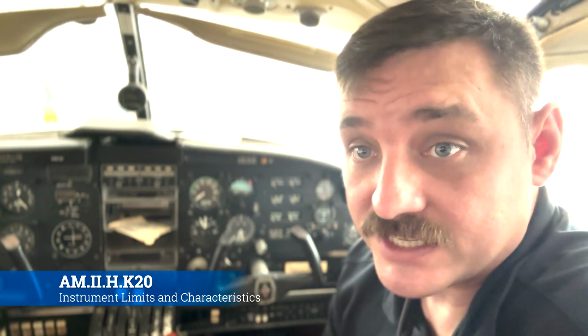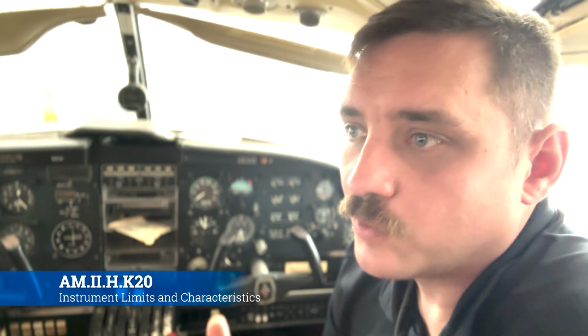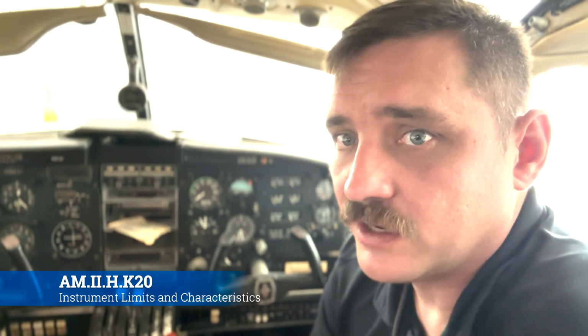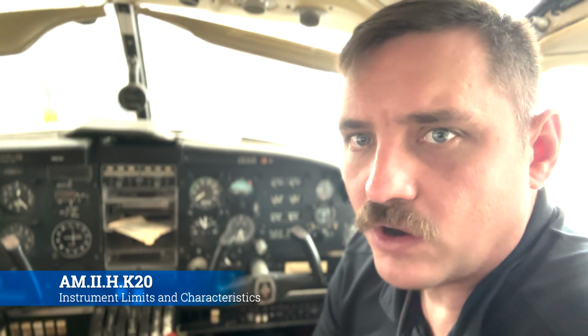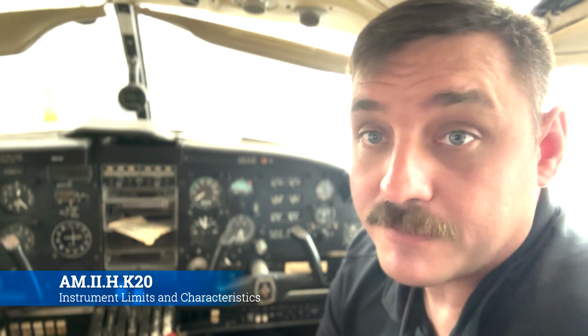Just like we were troubleshooting yesterday with the light, it's very similar in that you want to swap out components and see if the issue follows, and then from there go about trying to understand what information is being produced inside of the airplane that's being fed to that point of data collection that's causing it to be all weird or produce the effect that's happening.